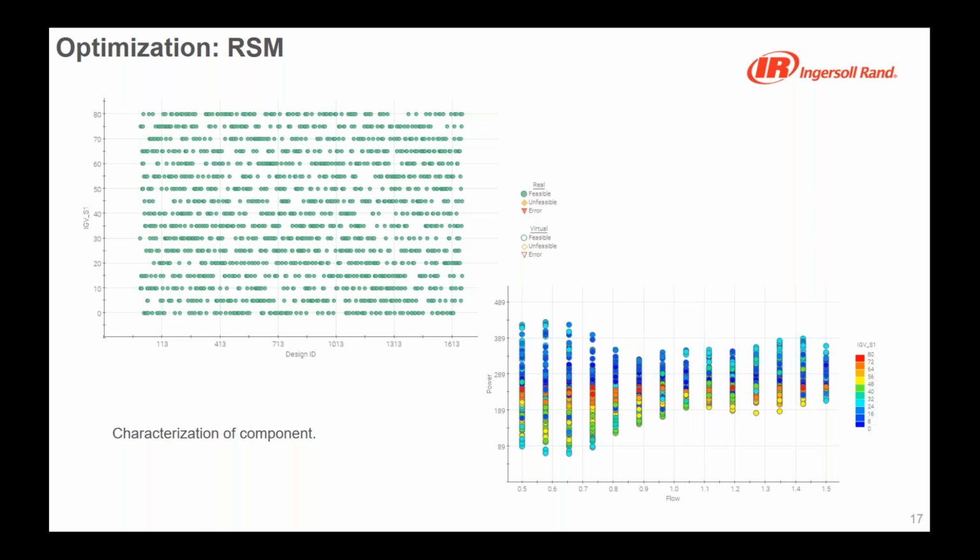And actually, the more interesting piece is the graph at the bottom, as you can extract from the data a correlation chart that tells you flow, power, and IGV angle, how they are correlated to each other, and can give you an idea, for example, of where you have to concentrate your design effort in reducing, for example, inlet pressure drop, or which are the cases that are more delicate. So which are the cases where you're not going to spend any effort in optimizing your design.